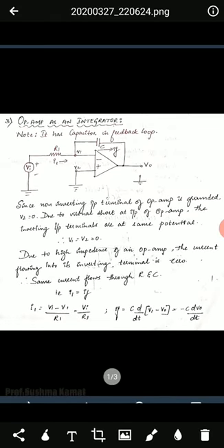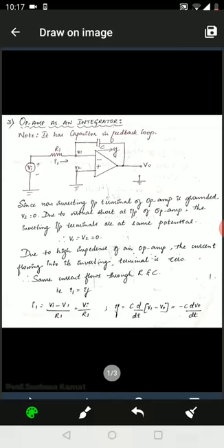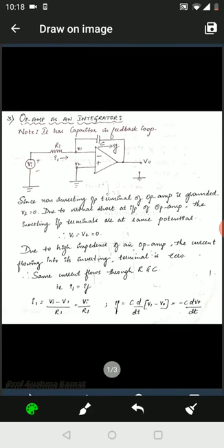So this is the circuit diagram for Opamp as an integrator. When you look at the circuit, you will understand that every other part is same except the feedback. The feedback was considered as the resistance in the previous cases, but in integrator the feedback will be considered using the capacitance. So in the case of differentiator, both of these will be interchanged. This is the hint that I am giving to you about the circuit. In an integrator, in the feedback there will be a capacitance, and in the differentiator at the input there will be a capacitance. So now let us begin.